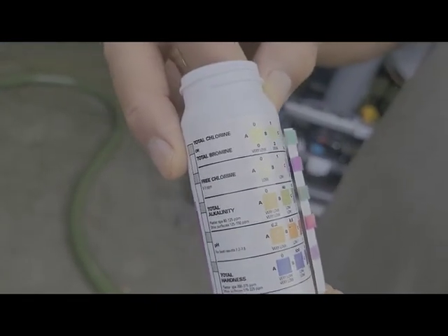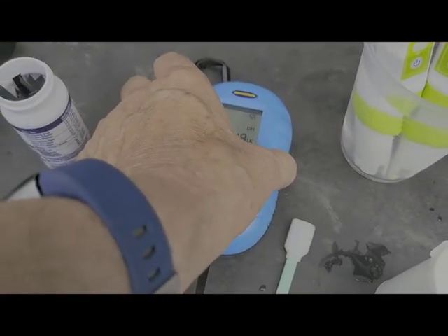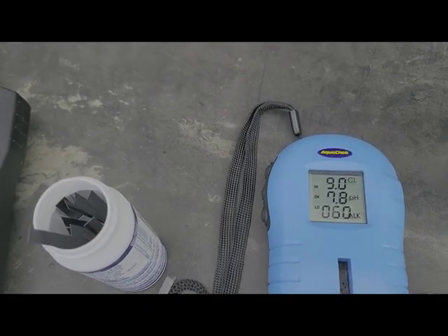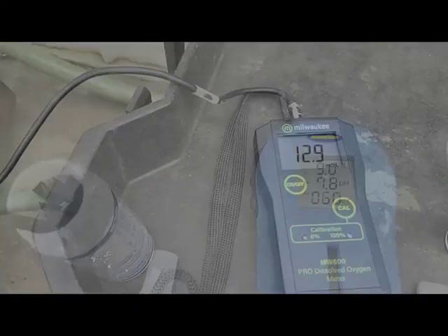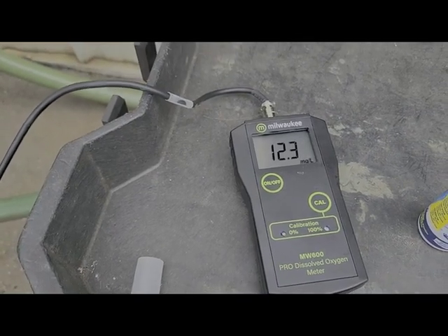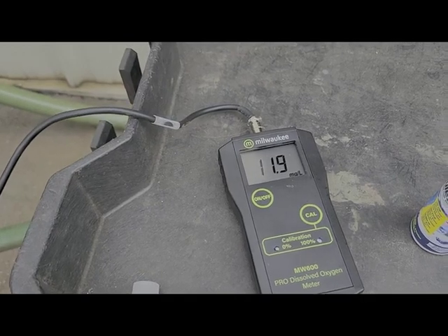There it is, total chlorine and free chlorine, and obviously off the charts. And here's my little electronic gizmo. It's going to show 9 ppm of chlorine. By the way, the chlorine smell was intense. And here's the final dissolved oxygen reading, which is probably around 11 or so, 11 and a half maybe. So that's where it's at.